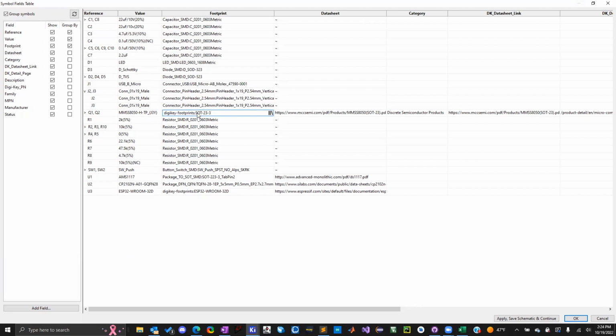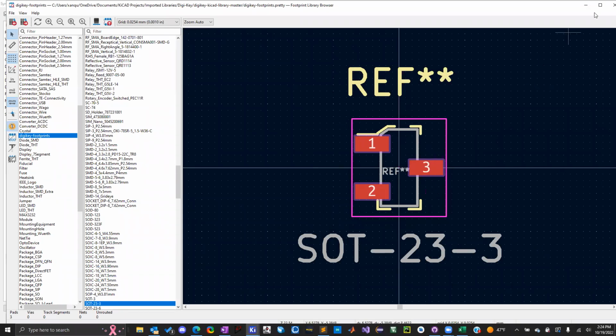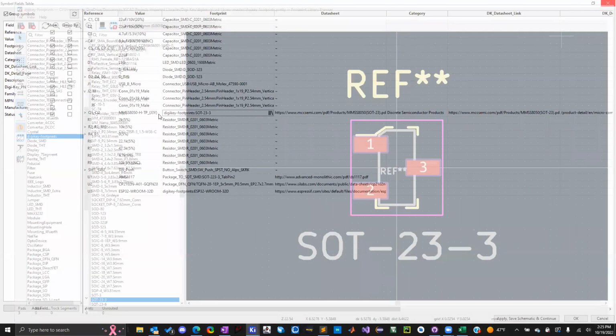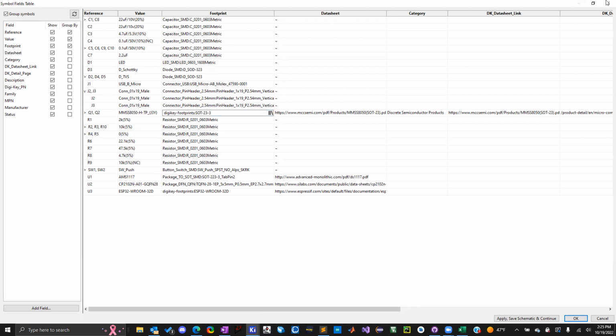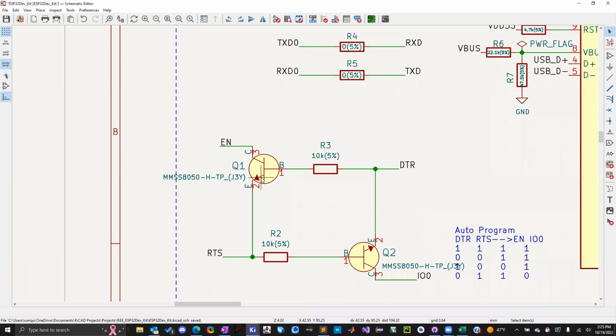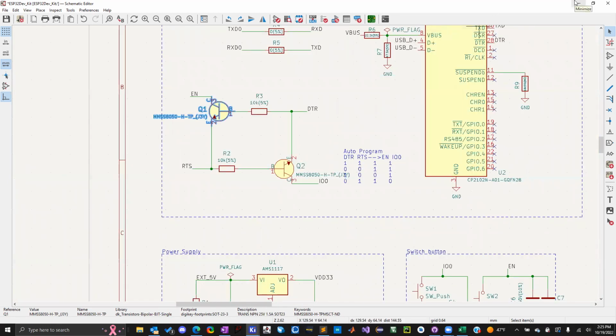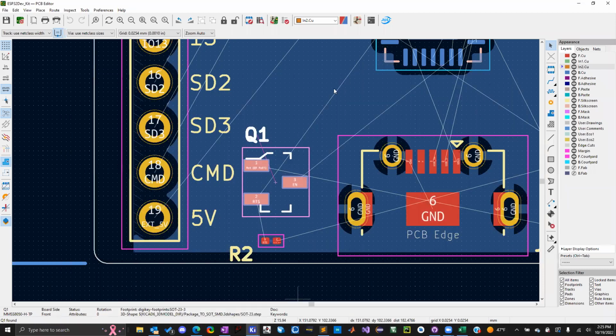For these transistors, the package type is SOT-23. That looks something like this. They're very small. So that's an NPN transistor, or is it a PNP? They are PNP. No, it's flipped. NPN. Wait, is the arrow pointing in or not pointing in? Okay, yeah, they are NPN transistors. With NPN, the arrow is pointing out, away from the transistor. If the arrow is pointing into the transistor, it's a PNP. Cool tip for you guys online.